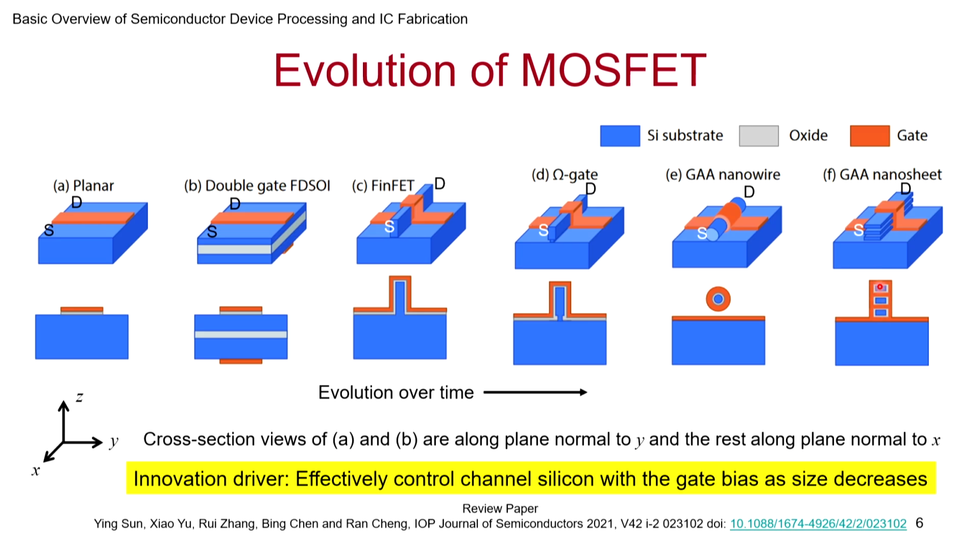So when you are contacting it, the silicon which is running in this direction under the gate region, around the gate region, that whole volume can be controlled very nicely by the gate. So this is how they went about making the better control. This way the short channel effects, the leakages that came as a result of the drain, whenever you turned it on, you had started getting leakage, you could minimize significantly.